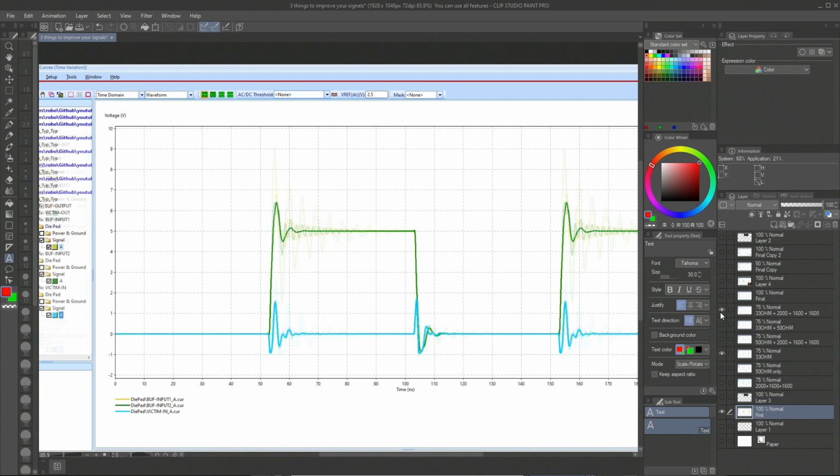Even when we use the 33 ohm resistor and a proper improved stack up, you can see it helps, but we still see the ringing. So definitely the length matching of the branches will help to remove this ringing. That's why we did the length matching of the branches, to remove this.